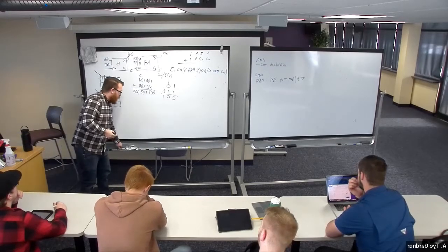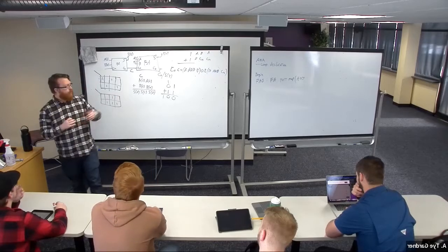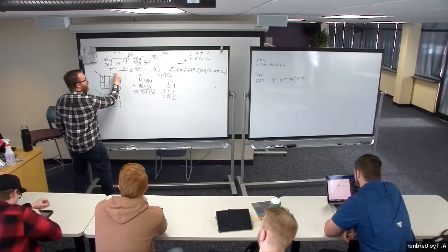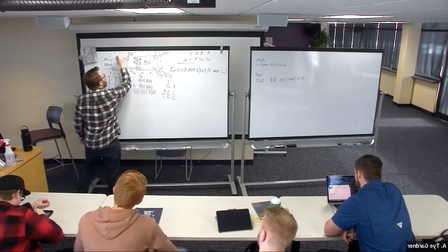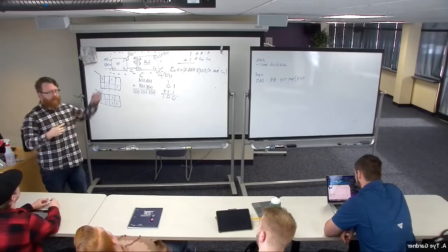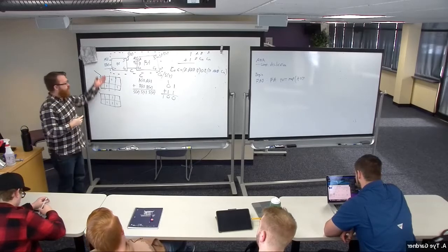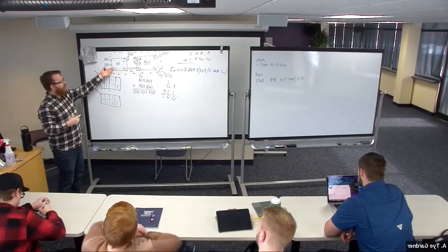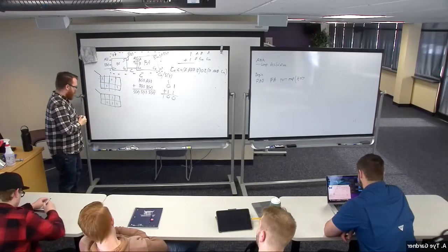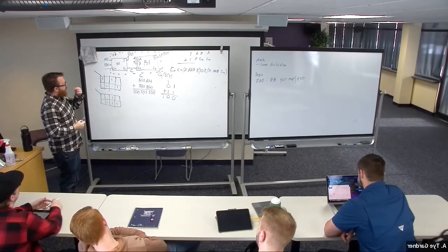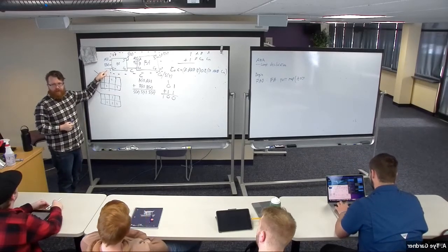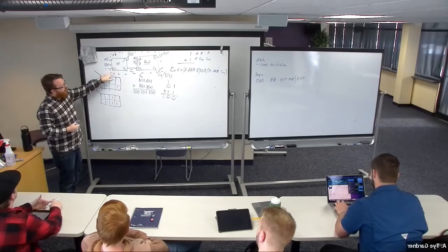But there is a caveat, which is if I want to use this 2-bit adder, like so, it's its own component now, right? Which is going to use other smaller components in a hierarchical design. It's just going to call, I need 2 of these guys in order to build a 2-bit adder. That's what this larger one is going to be called. Okay, but when I do that, I don't want to tie this carry in directly to ground inside of the 2-bit adder.